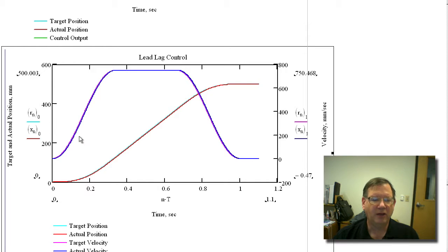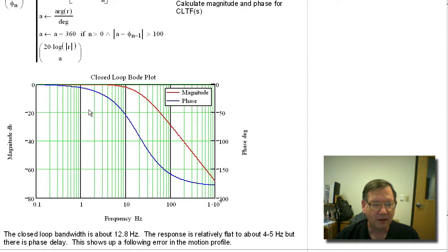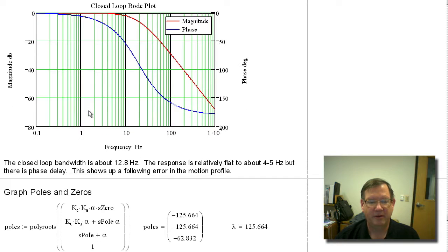So if you take a look at this, the frequency of acceleration up and down has a period of 2/3 of a second, or a frequency of about 1.5 hertz. So what we need to do is look at this point right here, and you can see that the magnitude is good, but we're going to have a little bit of phase delay. And that's exactly what we see.